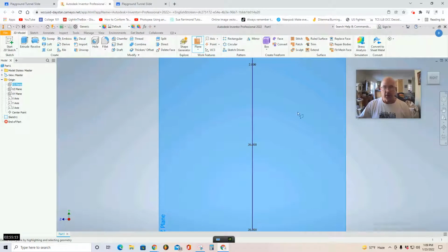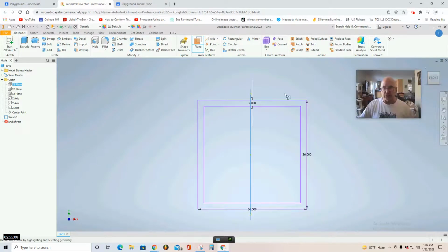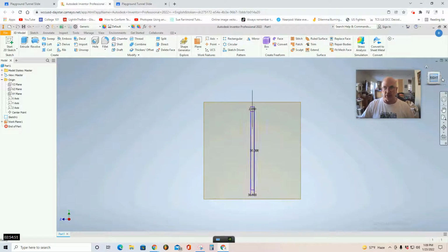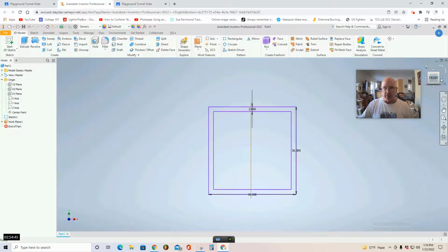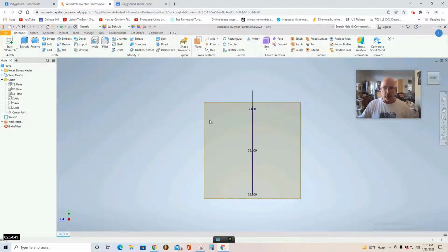Click. You're going to want to then turn your profile so that it faces you again, and you'll see these little yellow handles. Just drag it, and then you can just drag it back, or enter 0, and then the checkbox. Now you'll see you can just turn it 90 degrees again to the right view, and your plane is there facing you. Again, here's your front view, here's your right view, and in the right view, you want